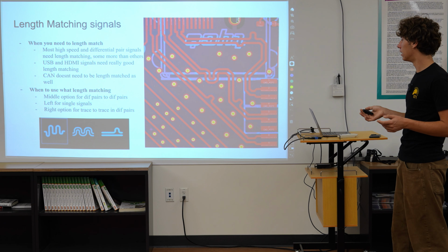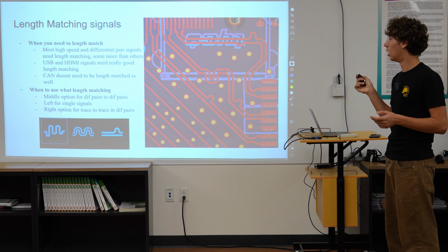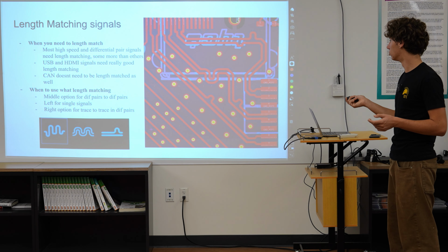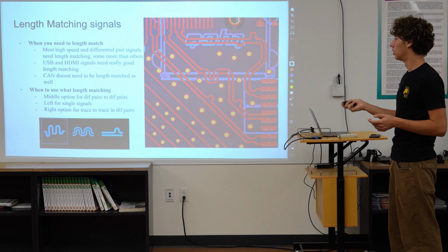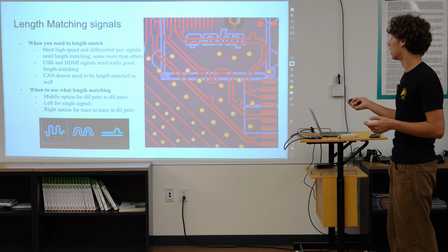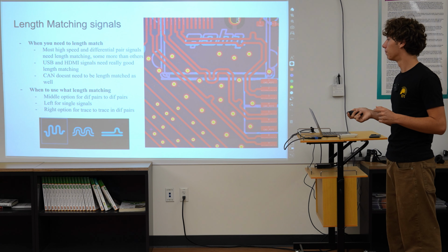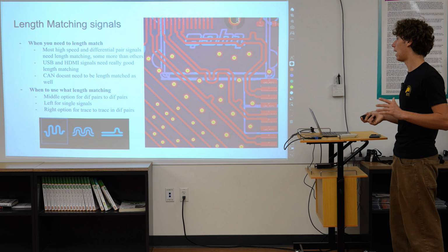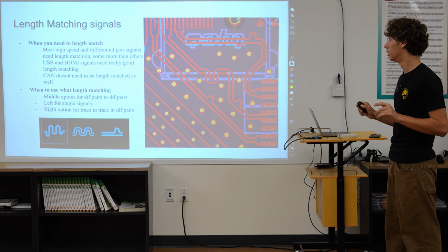I haven't really ended up using that too much. For this one, it's going to move both of them. So this wire right here is a lot shorter than these 2. So I put one of these right here to make it a little bit longer, and then it'll be length matched. Definitely when you're doing length matching, instead of doing everything manually, you can put into KiCad how long you want it to be, and that'll make your process a lot easier.